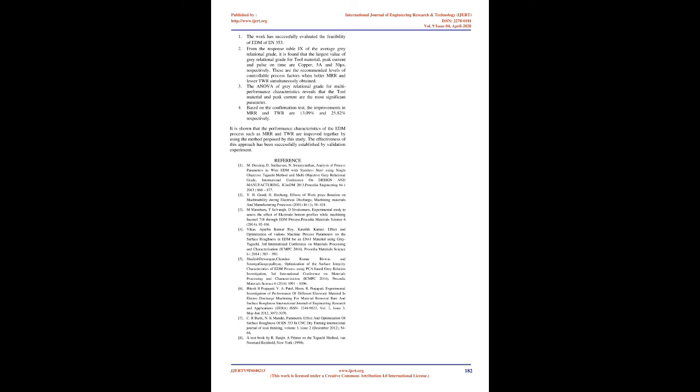Based on the table, MRR is accelerated from 0.430 to 0.4863 g/min, and the TWR is decreased from 0.0213 to 0.0158 g/min. The corresponding improvements in MRR and TWR are 13.09% and 25.82% respectively. It is clearly shown that the multiple performance characteristics in the EDM process are greatly enhanced through this study.